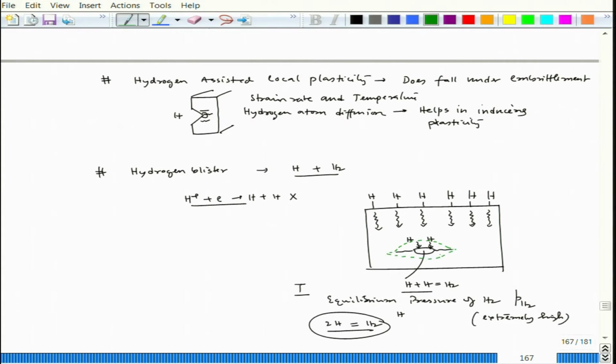Okay. So, this crack is actually observed mostly on the outer surface, not the internal surface. You could see that this particular crack is not due to external stress, rather the stress is coming from extremely high pressure, and that pressure leads to internal stress, which leads to a failure of the material. So, this is hydrogen blister, where hydrogen diffusion and then recombination of hydrogen takes place.